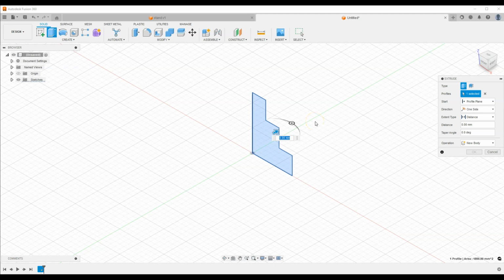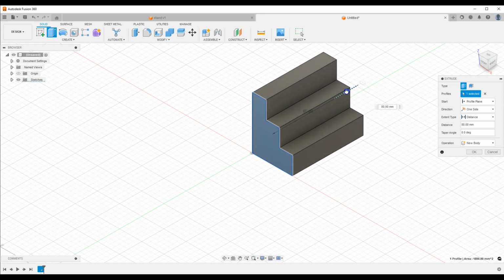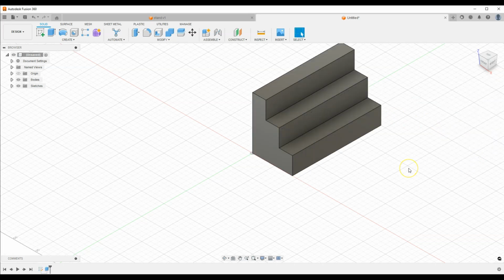And to specify the length of the extrusion, you can do it with this arrow. You can just drag this arrow to the appropriate value, or you can specify the length of the extrusion by entering the appropriate value in this field. Let's enter 100 mm here and click OK to confirm. And in this way, on the basis of a 2D sketch, we got a 3D solid, and now on one of these faces, let's create a sketch on the basis of which we will add a hole.